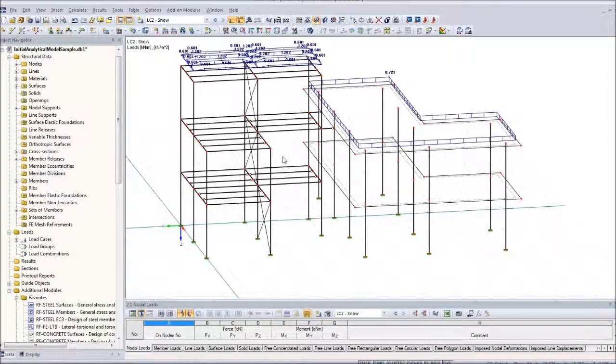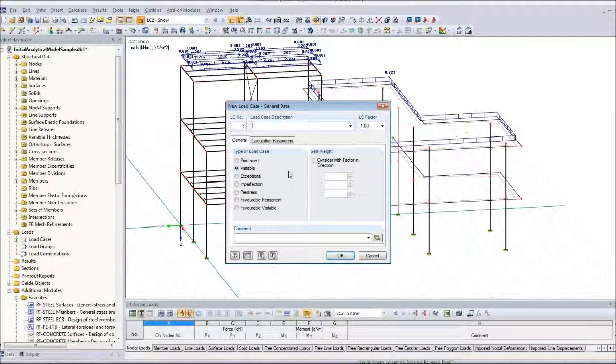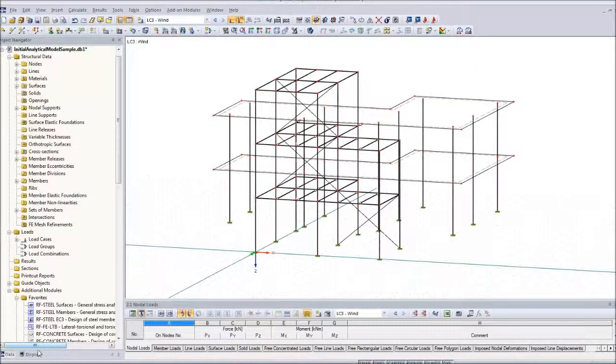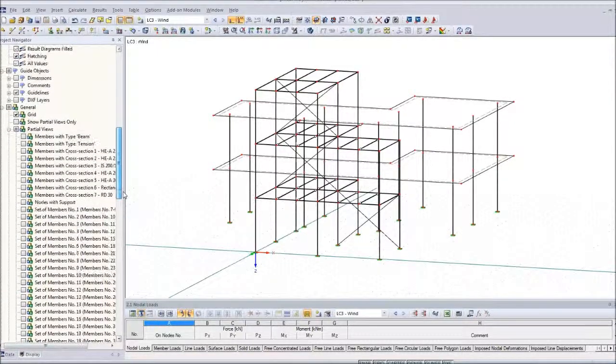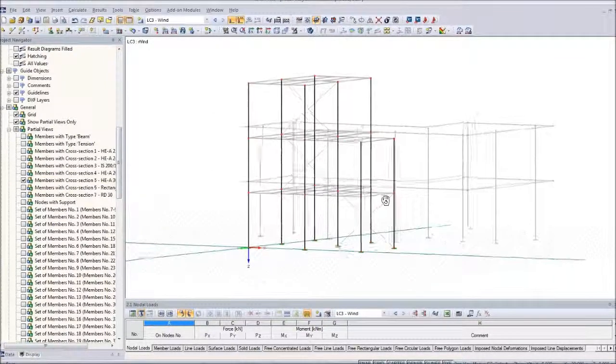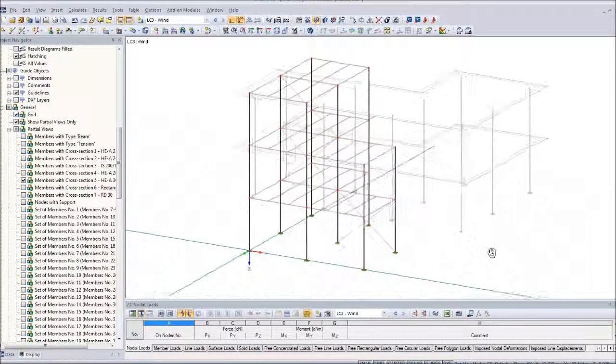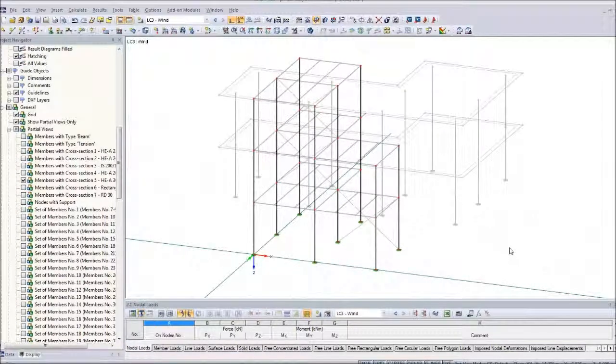Okay, next thing will be a new load case for wind load. Wind load, there are also generators, but in the general case of buildings you will just have to do it manually or semi-manually. You can maybe use the wind load generators for parts, and if they are of general shape, then you will have to do manual input. But it's not as difficult as you might think.